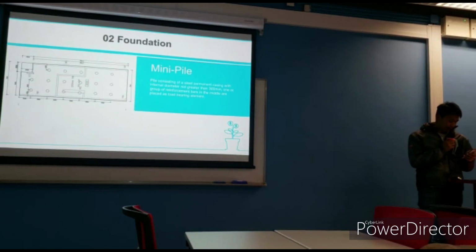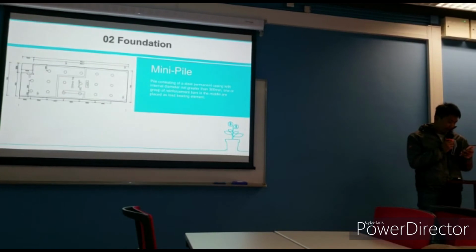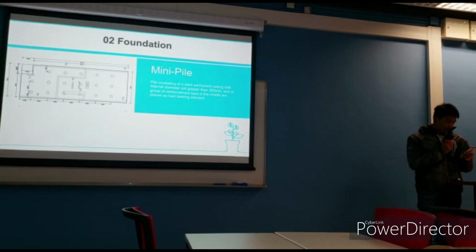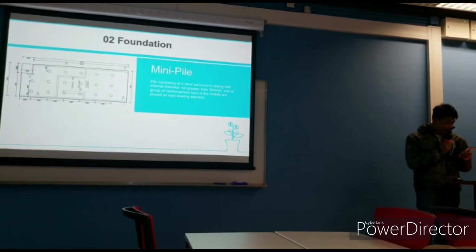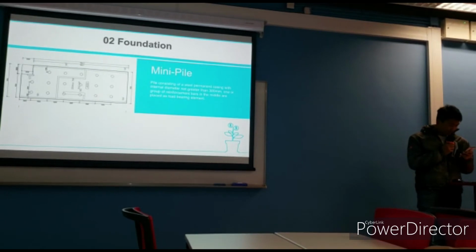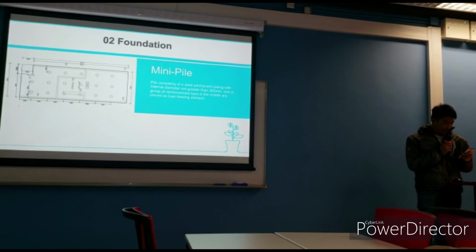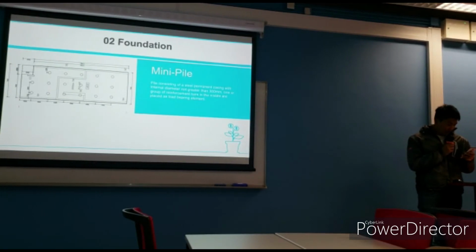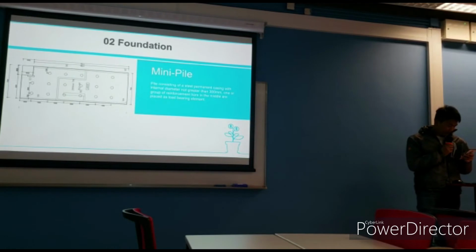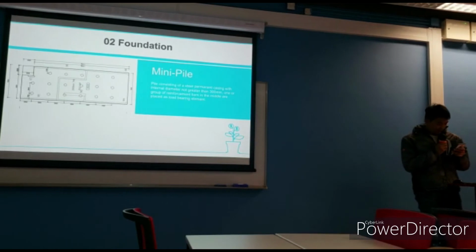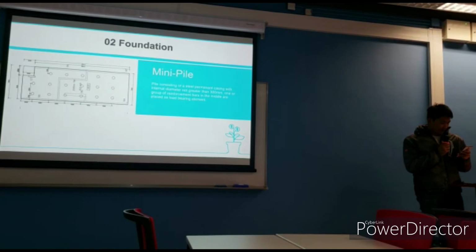Foundation is considering the proposed development of a low-rise building, and the bedrock level is estimated to be around 20 meters to 25 meters below the ground level, and therefore mini piles are proposed. The proposed building will be supported by mini piles, and the pile cap thickness will be 2 meters. The proposed mini piles are decided to be socketed into the strong rock. The rock socket capacity of the mini piles was checked against bond strength between grout and rock, and grout and steel, with 6 meter socket length, which will be provided for the pile cap in the foundation scheme.